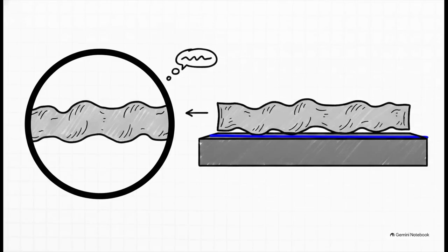But wait, here is a massive conceptual hurdle that so many people miss. The physical part itself is not the datum. Remember, the physical part is bumpy and flawed. A true geometric counterpart is what establishes the datum. When you reference a flat surface on a drawing as datum A, the actual datum A is the mathematically perfect plane of the granite table you sit the part on, or the perfectly straight axis of the chuck holding a cylindrical part. We measure from the perfect counterpart, not the imperfect physical surface.